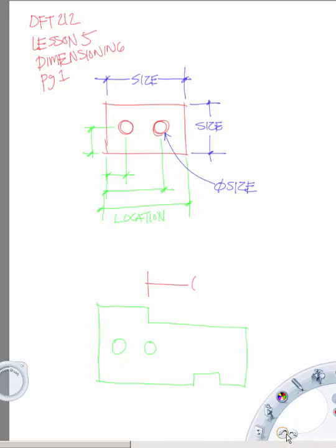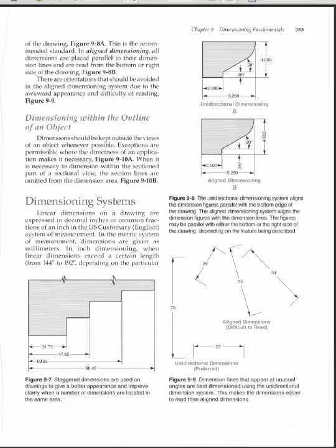So we might have an X value in imperial and in parentheses the metric equivalent, which is no big deal. The CAD package can take care of that without a bit of problem. But it's important just to realize that it's often necessary to dual dimension, just for multiple possibilities. And typically most manufacturers nowadays work in decimal inches or have completely switched to the metric system, and probably will over time.